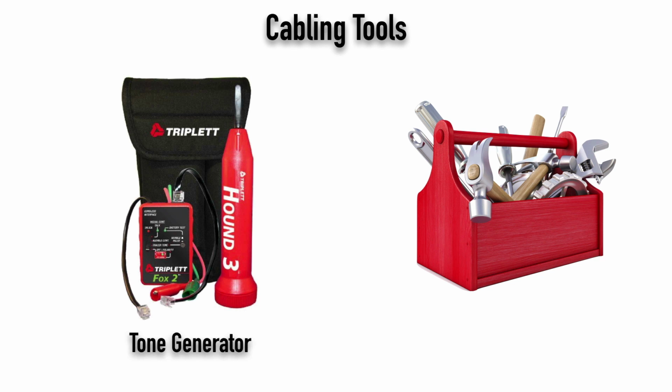Well, what you could do is use what's called a fox and hound or a tone generator. You generate a tone on one end and then you take what's called the hound in this graphic and you can go to where you think the cable should be coming out and you can just hold this little hound close to the cable. And if it's the right cable, it's going to start making a noise. You'll be able to audibly hear it on a speaker. And that's a way to identify cables in one room connecting to cables in another part of the building.